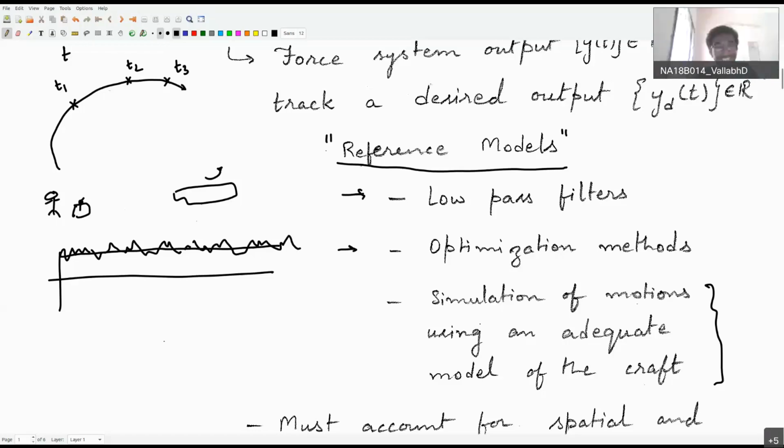These sort of things start to happen primarily because there is a dead band and we are kind of slightly over the dead band. So the propeller actually is getting a signal as if, come on, keep rotating, although we have left the joystick completely. Right? But when we put this through a guidance system, then what happens?